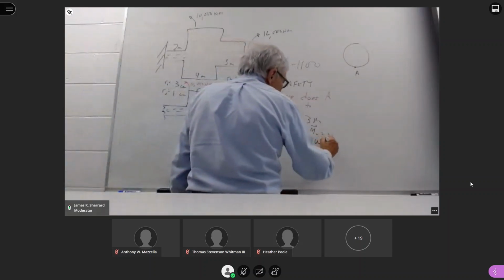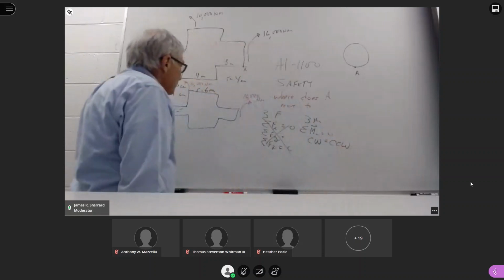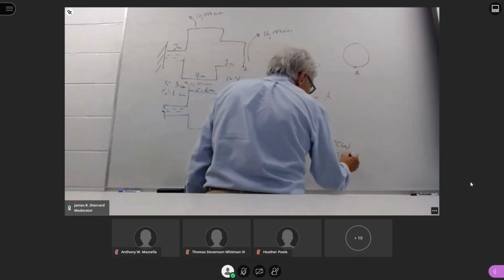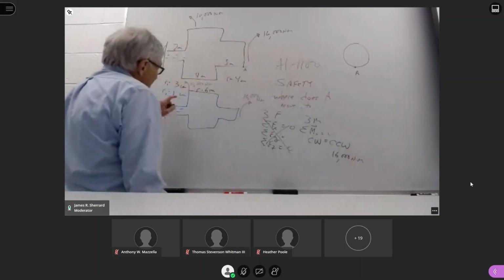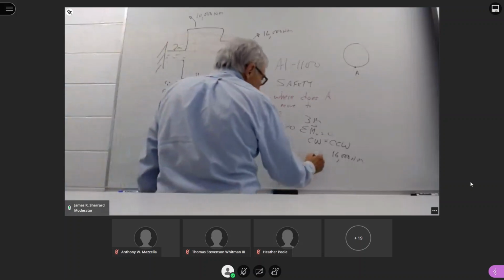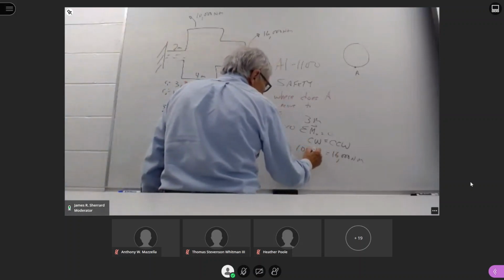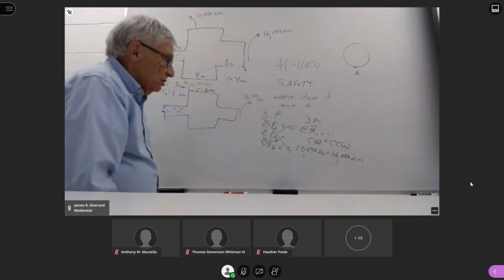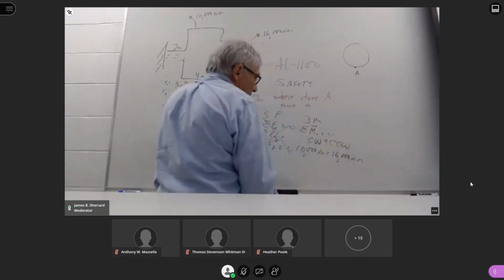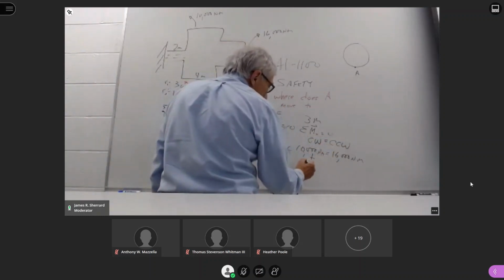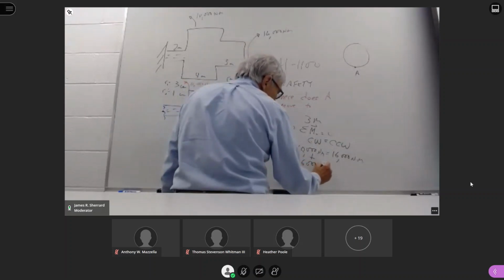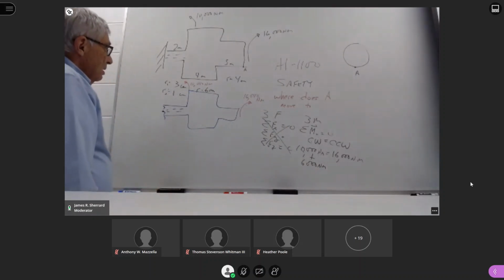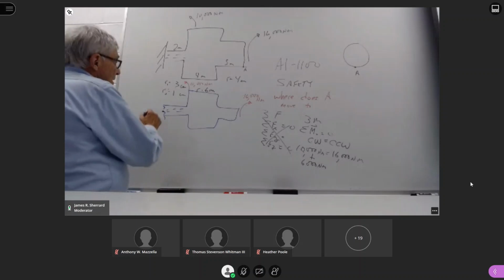And we know that clockwise has to equal counterclockwise. So in looking at this, for clockwise, we have 16,000 down on the end. Here we have 10,000 counterclockwise. So 10,000 does not equal 16,000. So in order to make the clockwise equal the counterclockwise, we have to add the difference between these two, which is 6,000 Newton meters, to this rotation.